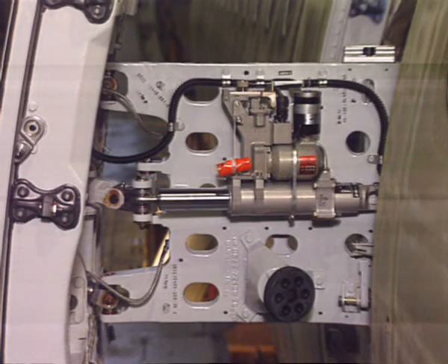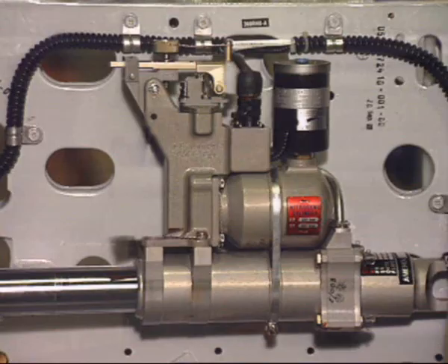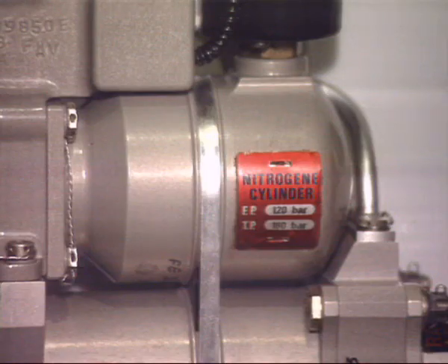The door damper hydraulically limits the speed of the door under normal operating conditions. Under emergency conditions, the door damper acts as an actuator to open the door rapidly. To initiate emergency operation, the release lever is raised by door upward movement. The percussion mechanism breaks the diaphragm of the pressure accumulator and causes the nitrogen gas from the pressure accumulator to extend the actuator piston rod.